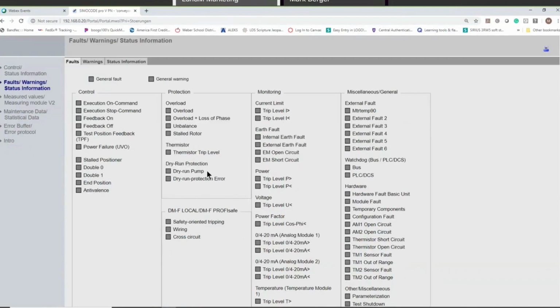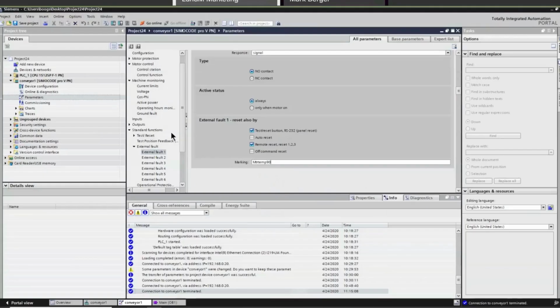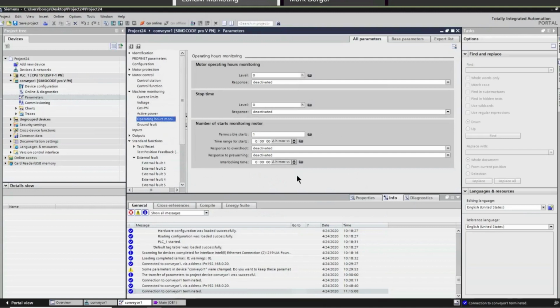Because we can also, in the software, set up a PM. A lot of PMs on motors and so forth could be done with calendar dates. But in my case, with the SIMOCODE, I could come in here and put in 600 hours of accumulative running on the motor.